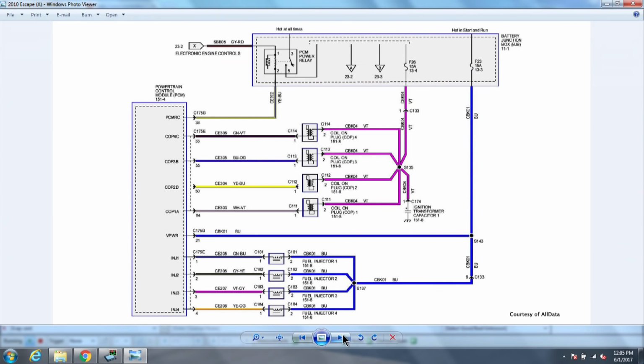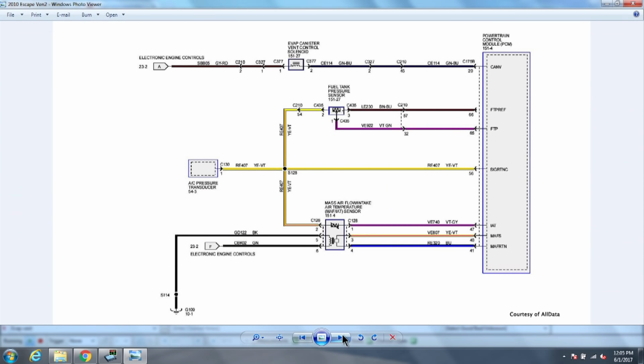Now let's look at our pin A. It comes from here, through here to our PCM power relay. So our PCM powers on the relay, grounds this side, and sends power through pin A. Fair enough. So our PCM power relay is basically the input power for our purge solenoid. Let's see what our vent solenoid is. Again, pin A, so probably back to that same place. Vent control solenoid looks like here, ground side controlled, I would guess. This would be ground side controlled.